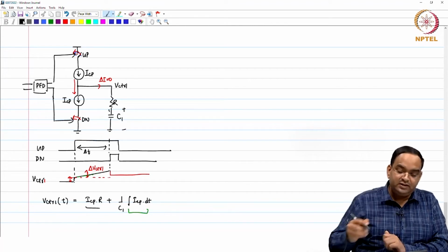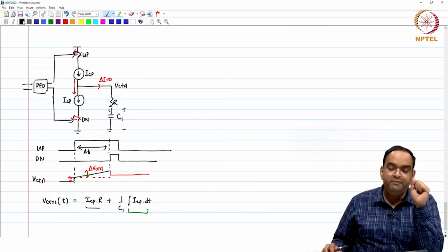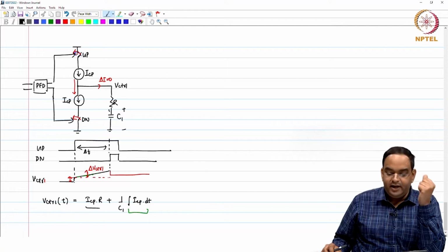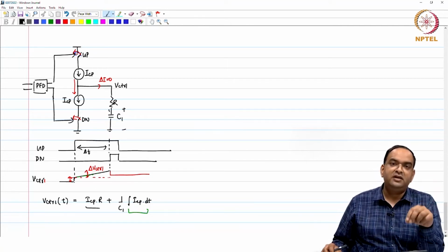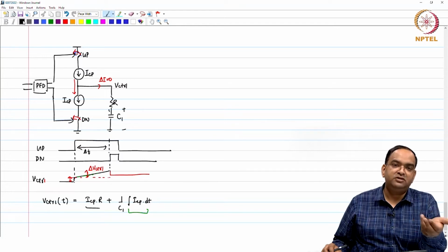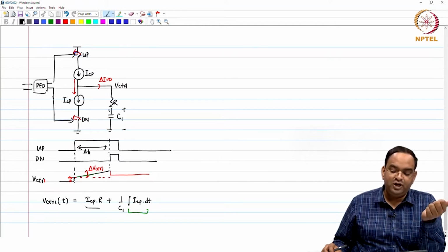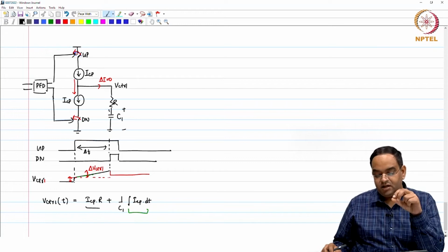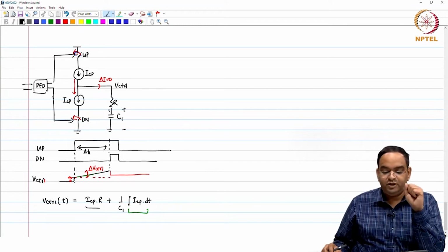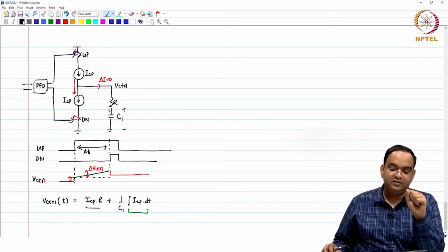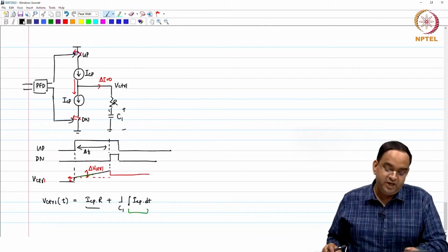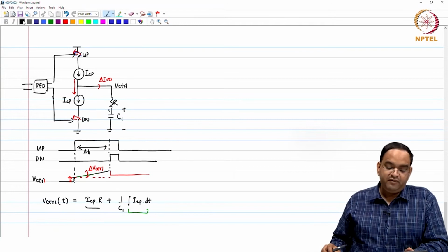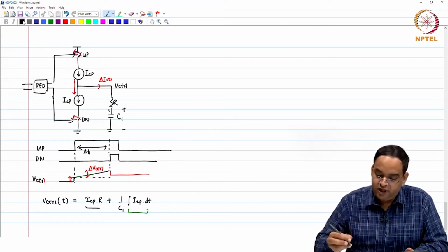Okay. So, this particular implementation appears to be easier than the implementation which you just saw before using voltage sources, right. So, what we are going to do is use this particular implementation in our PLLs to convert the PFD output to control voltage.